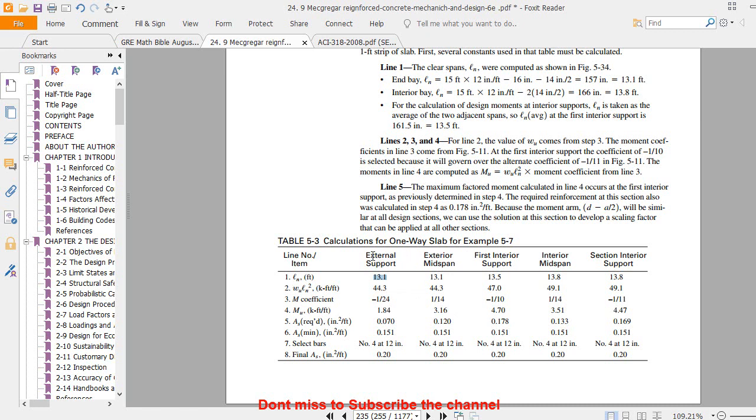Now external support 13.1, exterior mat span 13.1, a first interior support 13.5, which is the average. And then remember, this is the average, 157 plus 167 divided by 2, and this is again 166 inches, and so on. WU ln square, we already calculated WU; just take that WU which we calculated in the first step and multiply with this 13.1, you got this one. Similarly with this, you got this value, and so on.